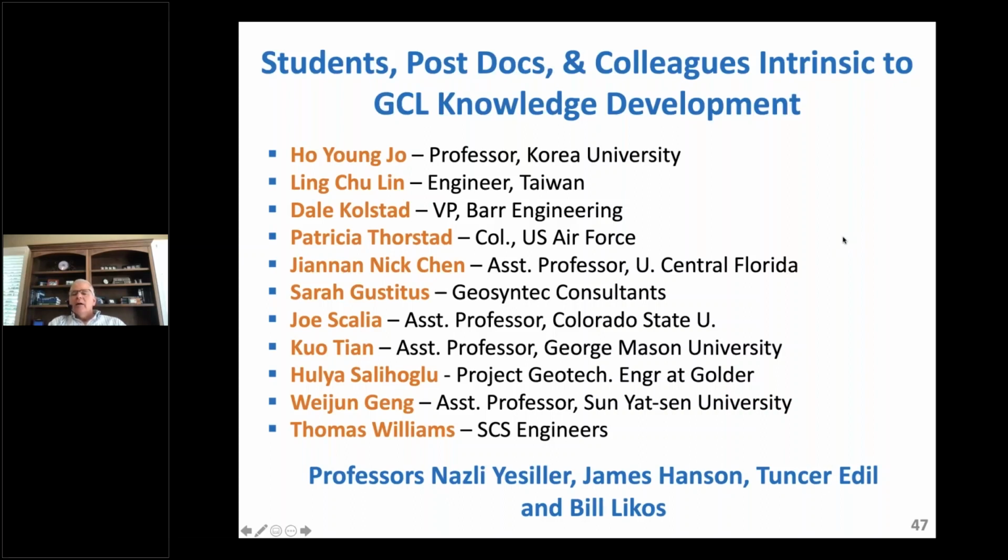I appreciate that. Question from, it looks like, Aisha Jacob: how to prevent calcium diffusion from underneath the GCL to prevent crystalline bentonite structure? This is a very similar question to Sean's earlier. Get the subgrade as moist, optimum or 1% wet of optimum if practical, and that will allow it to hydrate before calcium exchange will become significant. And look for the case history in the file share by Scally et al. 2017. That's our case history from the Barnwell, South Carolina field site, which illustrates that really nicely.